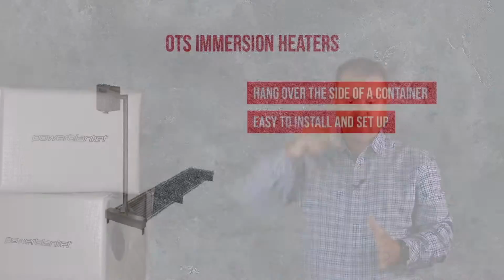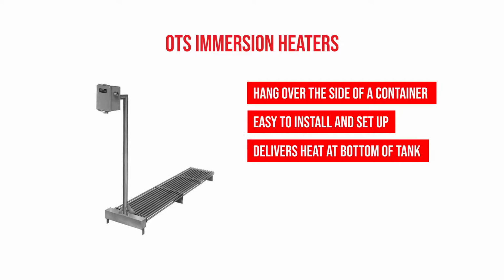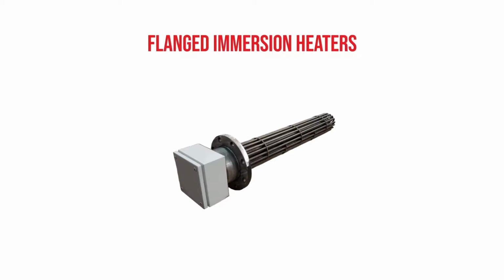The most common configuration is actually an L-shaped. So the long side of the L typically isn't heated, but the L side is. And so really it just matters how you get down to the bottom of that tank. They sit on the bottom of the tank, they deliver heat into the process, and they're very, very reliable.